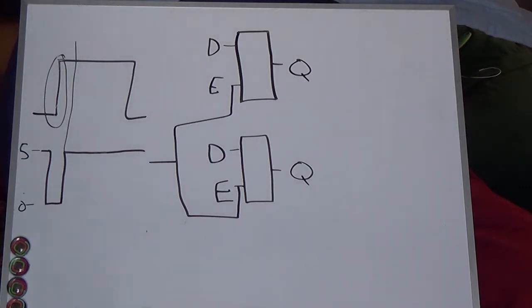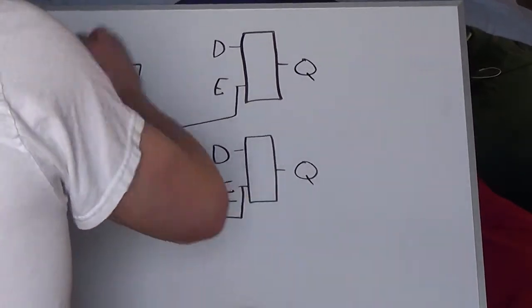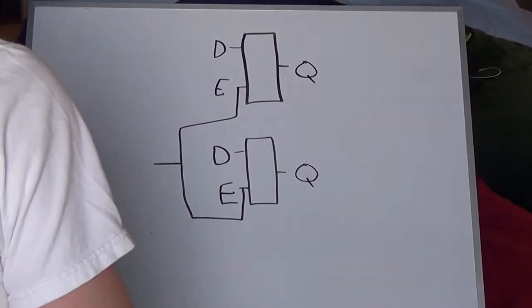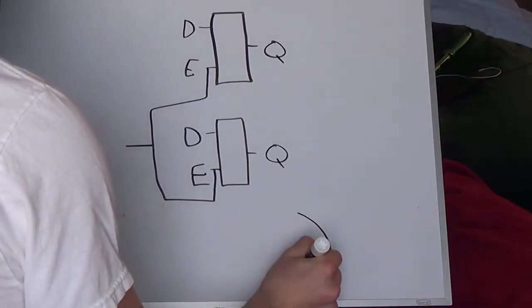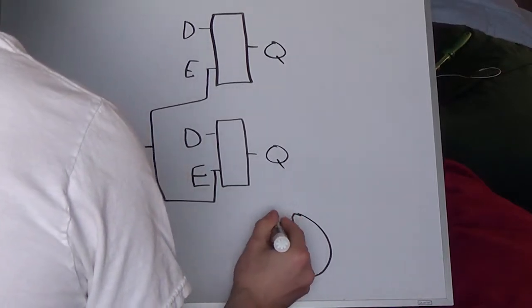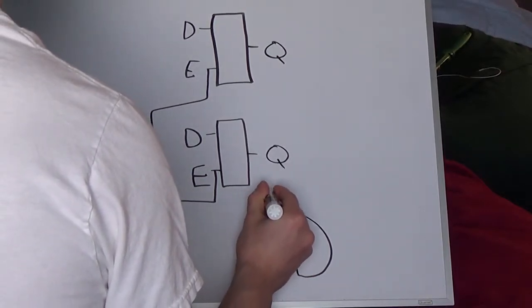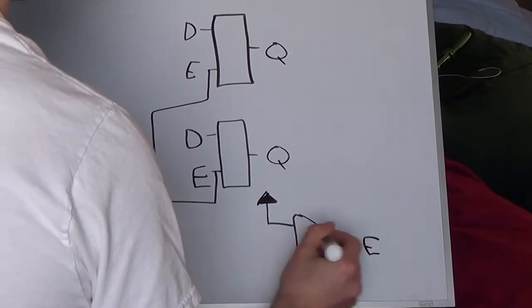The only problem I had with that, which I'll show you the setup now, I had extra 3-input NAND gates on the bottom of these registers because each chip holds three 3-input NAND gates. So this here was the setup I used. I had this actually run to the enable.